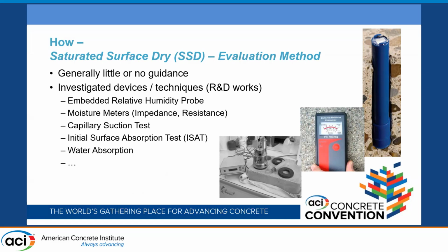Those are usually used in the flooring industry to assess whether the moisture content within concrete is ready for receiving the flooring. They're not directly a method to be used to evaluate SSD condition. There are a few other methods that are still in the laboratory stage, using complex equipment. They don't look ready to be used in the field as an easy, simple way to look at SSD.